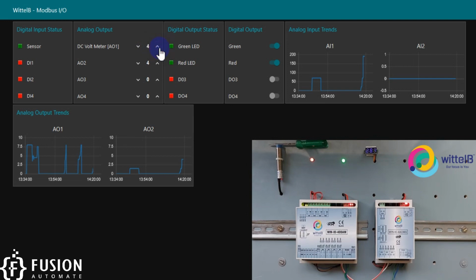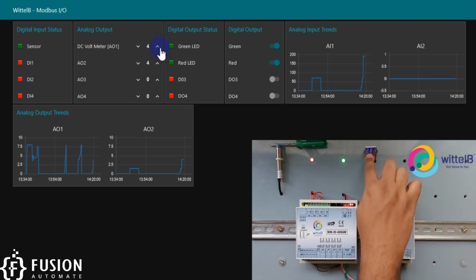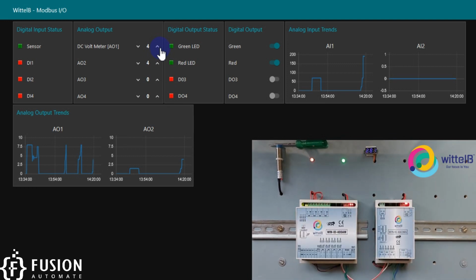Okay, so once I provide the 4 volt, you can see there are some blue LEDs on the 7 segment display. So it got the minimum voltage to operate. Now if I increase it more, you can see it is increasing. It's 3.24. Now if I go up to 8 volt, I have provided the full voltage here. You can see it's 4.70 volt, stable now.